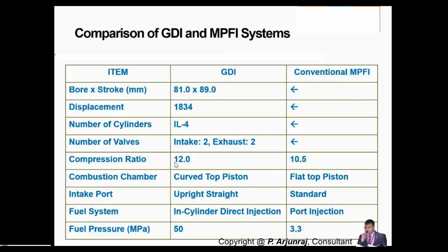It will result in a knocking sound, and even that problem can be overcome by a proper mixture of air and fuel. This comparison gives an overview that you're not going to get the knocking issue or abnormal combustion or abnormal pressure when you're injecting the fuel into the system along with the air.